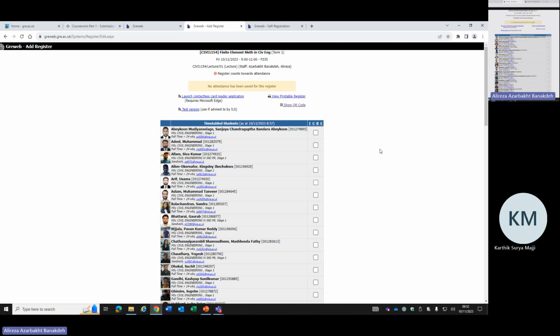However, this doesn't make a difference here because it's a truss, but it makes sense if it's a frame structure. So I'm going to assign restraint support here. You should assign restraint here, like translational Z should be ticked and rotational X and Y should be ticked.